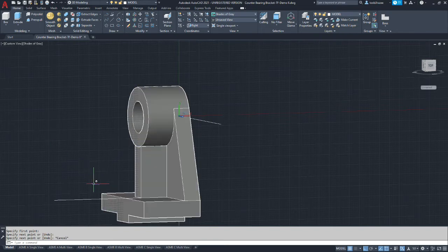I'm going to go ahead and draw another line from one of the corners of the model that's just going to be used for trimming. And we'll use that to trim this line off flush with the front of the part. So if we trim that, we now have the leg of our triangle contacting with the edge. There's a couple ways you could have done that. Alright, so now that we've done that, we don't need this line sticking out here.